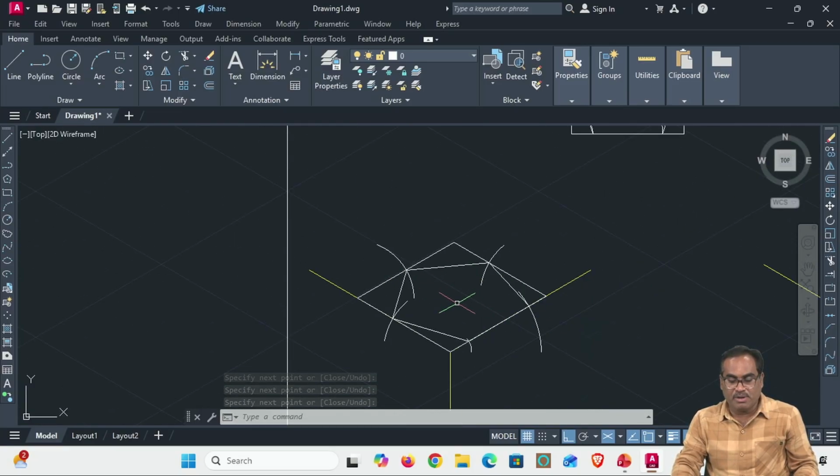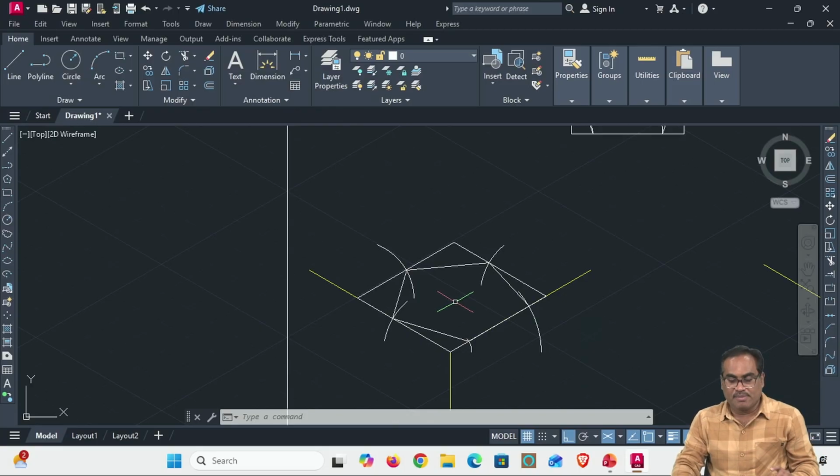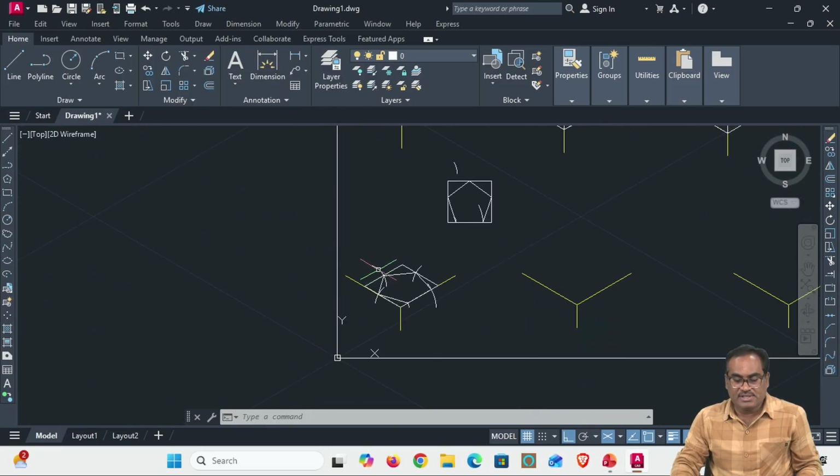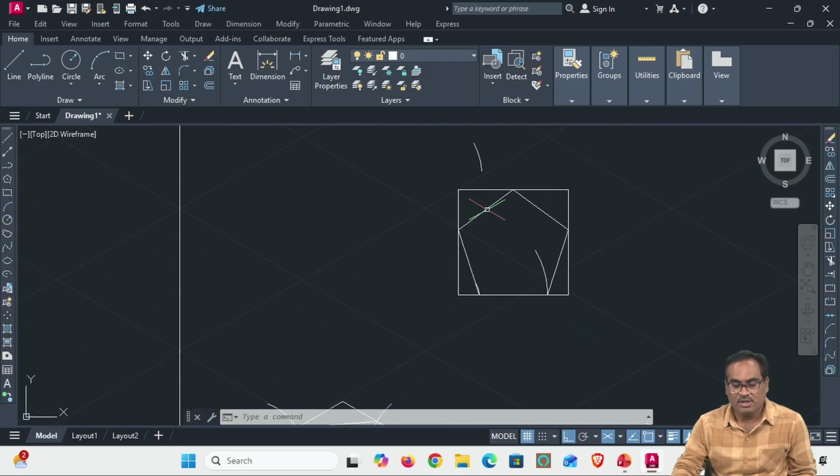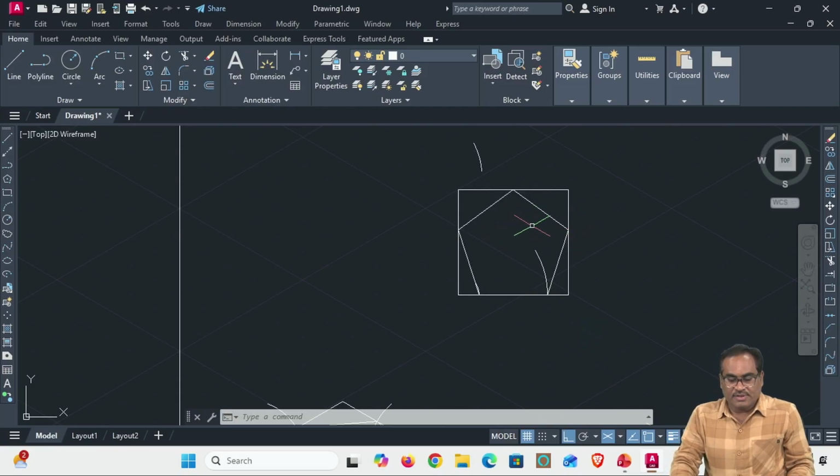Okay, now I want the center of the pentagon. I want to draw a pyramid, means I have to draw the axis from the center, how to draw. So if it is hexagon, if you join two diagonals, automatically intersection point, right? So in normal view also, for hexagon, identifying the center is very easy. So draw the two diagonals wherever intersecting, it's fine, but pentagon is little different. So first of all, how to identify? Okay, so here you can directly get geometric center.